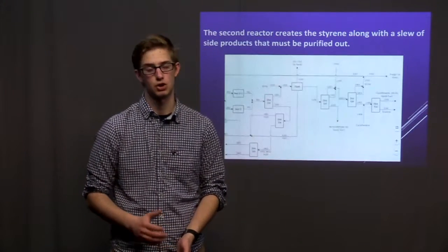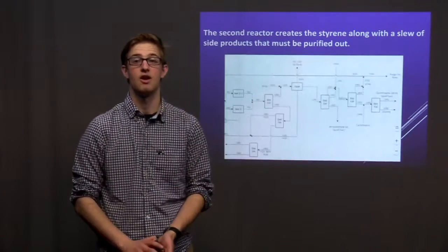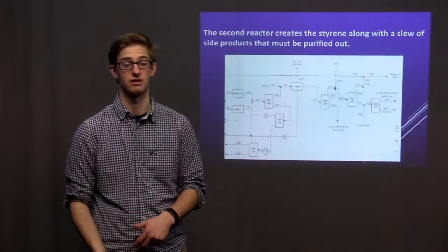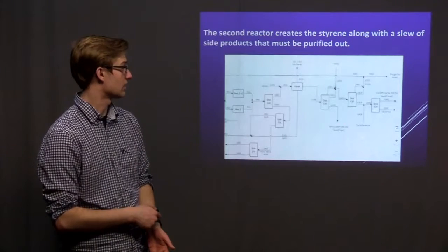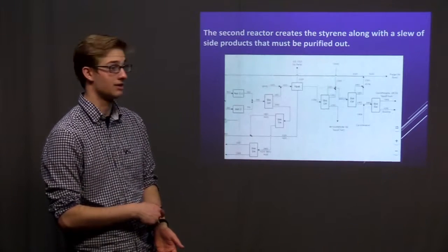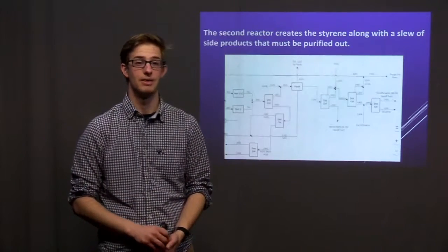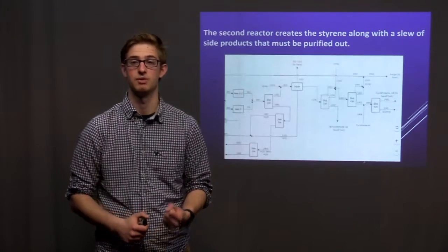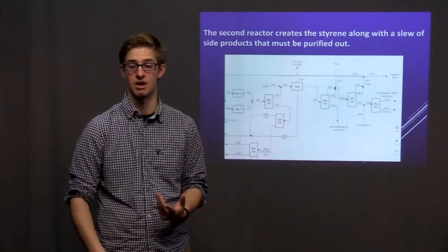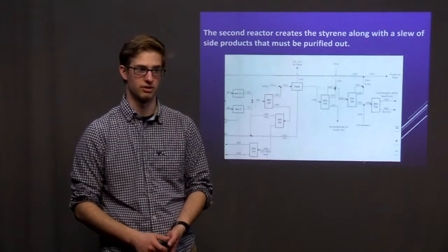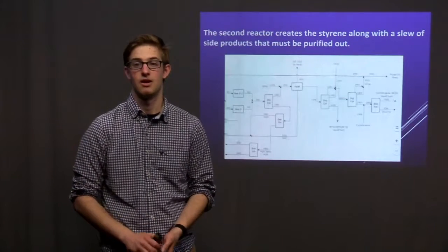The ethylbenzene is extremely difficult to get out from the styrene, so we had to use a system similar to extractive distillation. This took cyclohexane, and sends it through the distillation column with it. This cyclohexane allows the ethylbenzene to be pulled off the top and the styrene to come out as a pure product with over 99.9% purity and able to be sold.